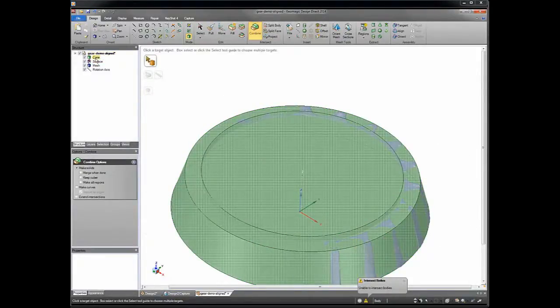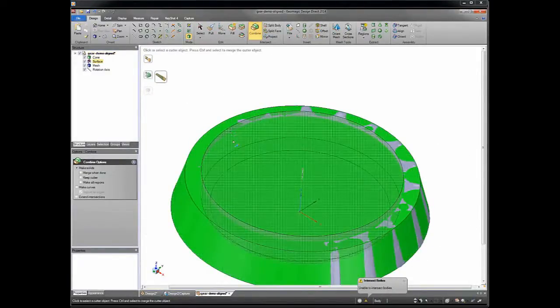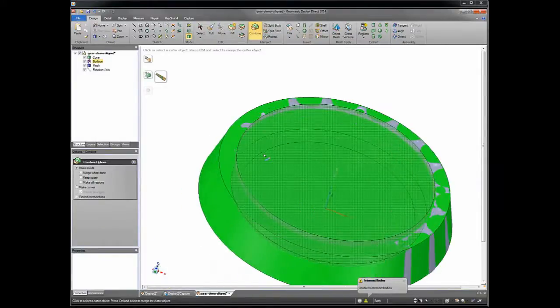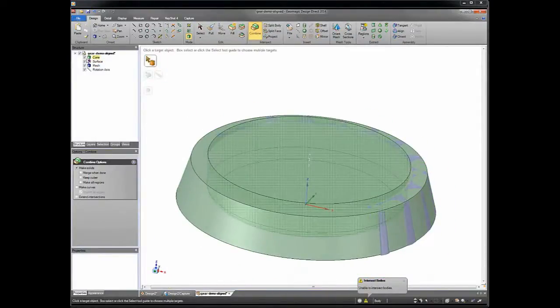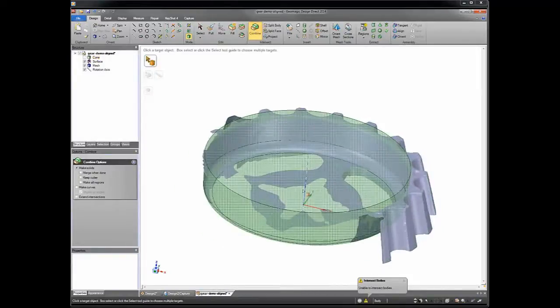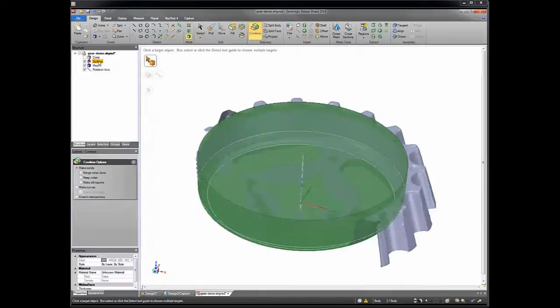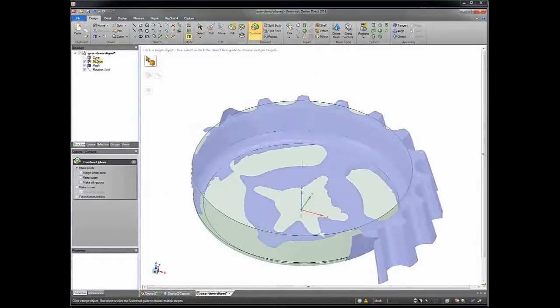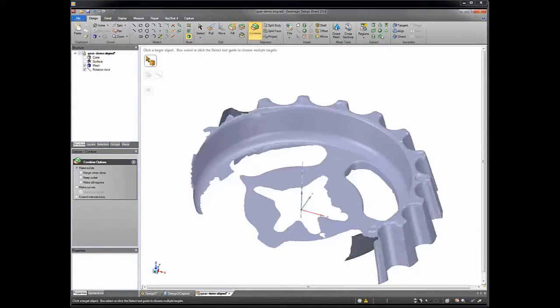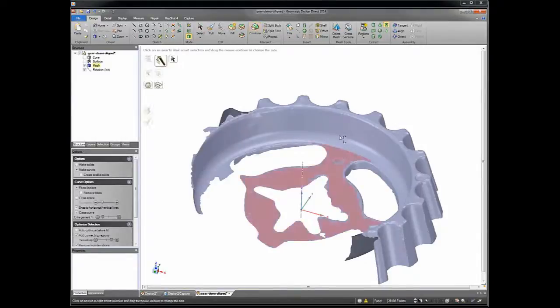Sorry, hang on one second. Well, I did something wrong. I was unable to intersect them. I think we might have a hole in that surface there. So what we'll do is let's delete that, and we'll just try it again. Delete our surface there. Let's go back into revolve, whip it up, and this time we'll just create the solid.